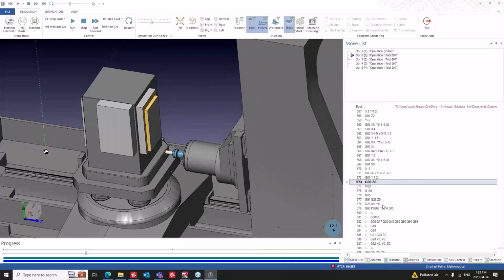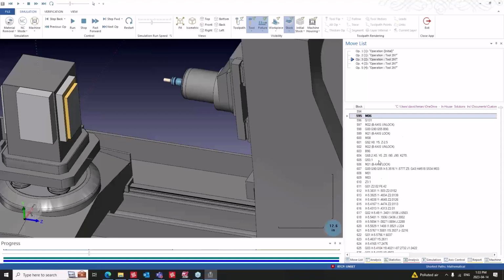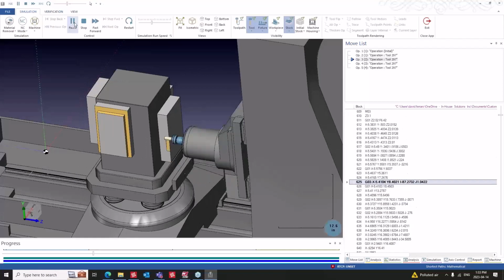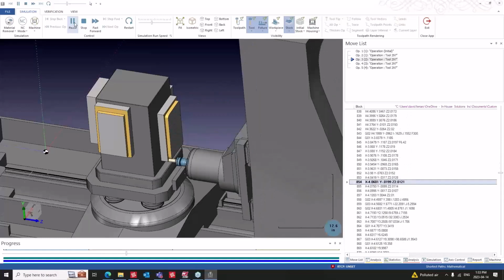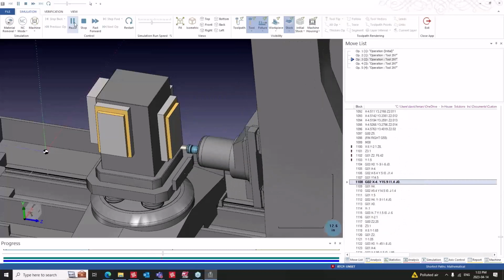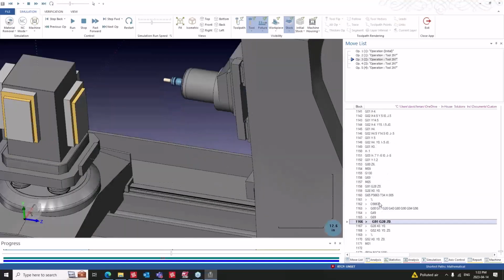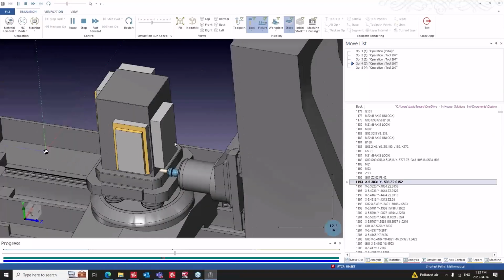And then you'll notice down here in the CNC code, there's your actual G65 for your P. So there's your subprogram there being called in. And then it returns to the main program there. And now our next origin up would be 55. So now it flips the cube, goes to and we're going to get the same type of program again. It's a little rough around the outside. And then 2 finish cuts. Okay, and then we'll go through this and we can see here, there's your subprogram again, and then back to the main program. And now we're at 56 now. So I'm just going to let this finish up now.